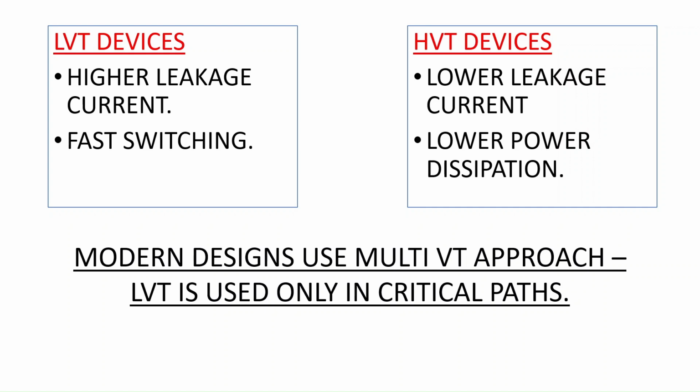On the other hand, the HVT transistors will turn on at a higher voltage. So when we see the high threshold voltage devices, the switching will occur at a higher voltage. So they will typically have a lower leakage current, hence lower power dissipation.